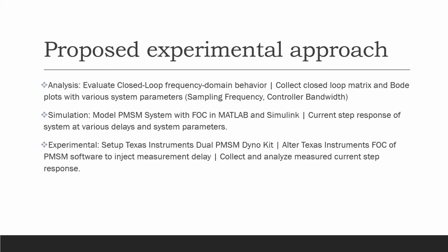So how have we approached this research? First of all, we need to mathematically analyze the system. To do that, we've evaluated the closed-loop frequency domain behavior of the system. And to do this, we've collected the closed-loop transfer function in a matrix form. And then we collect Bode plots of the system with varying system parameters such as sampling frequency and controller bandwidth.